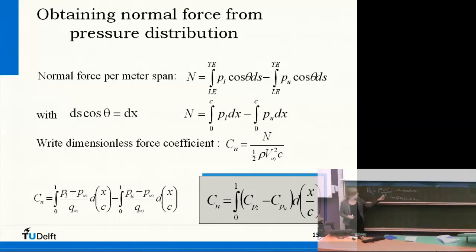Yeah, this L is a typical length. Reynolds number at L. So you have Reynolds X, I could say X along a plate, or Reynolds L. Reynolds is a bit flexible, what you fill in here as a length, a typical length. So for aircraft wings, you typically look at the chord. So it would be the C. The length that the flow flows over.